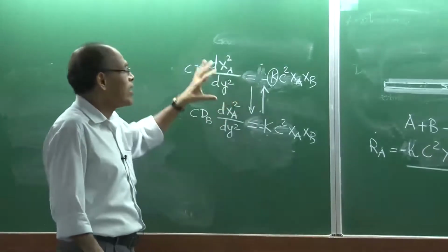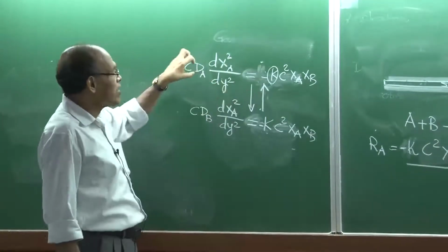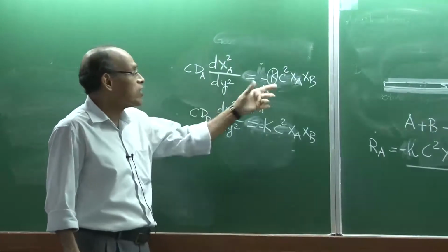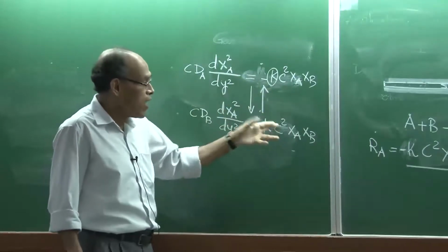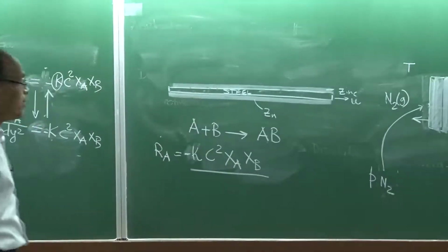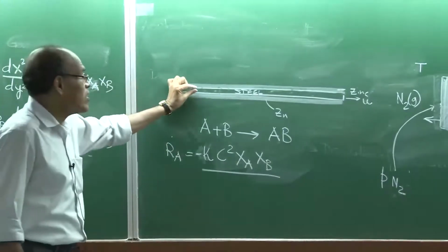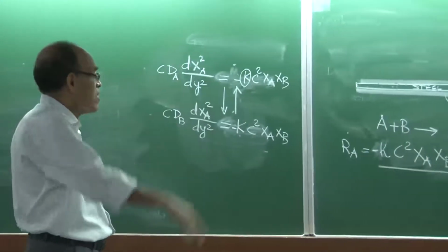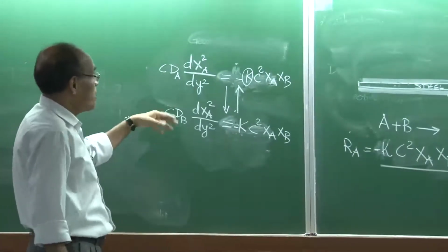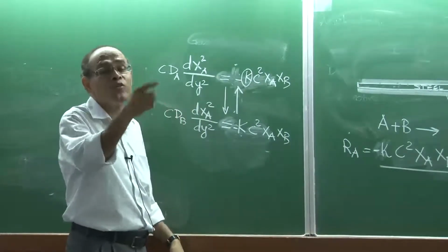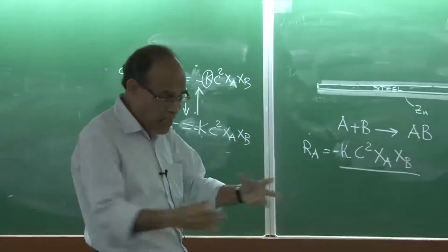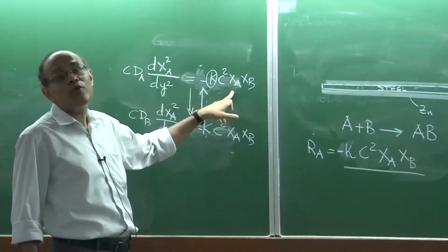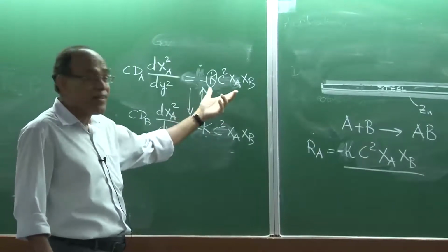But this is the way one can incorporate chemical reactions into the diffusion. Within the domain of diffusion, if reactions take place, that is the way to incorporate them, and that sort of physics may be needed in order to find out over what distance the diffusion is really taking place. It is not just pure diffusion. For example, if you want to find out how carbon is reacting with iron, in the context of gas carburization also, you should be able to consider the rate of the reaction.